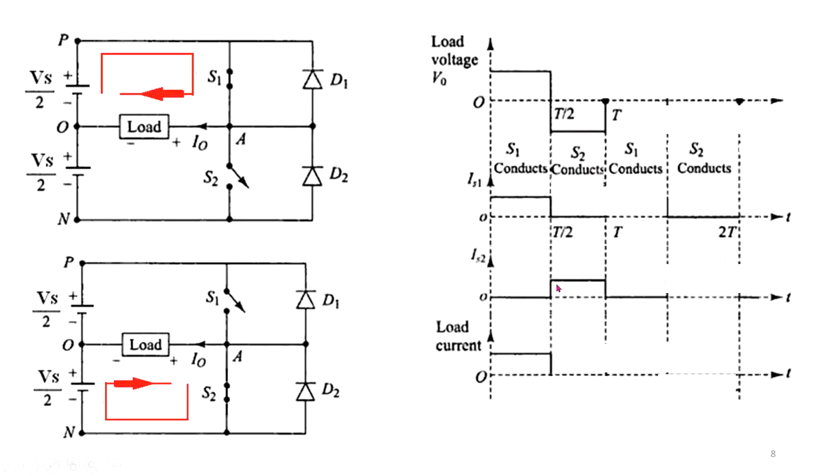S2 is like this. However, if you see the direction of the switch S2 current, it is flowing in the same direction as in S1, so it has the same polarity as the switch 1 current. However, in the case of load current, the polarity in the load is inverted. It is also inverted since the load voltage is inverted, so the load current is inverted. Okay, you need to be careful about this.